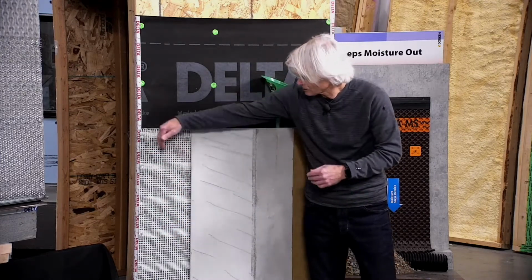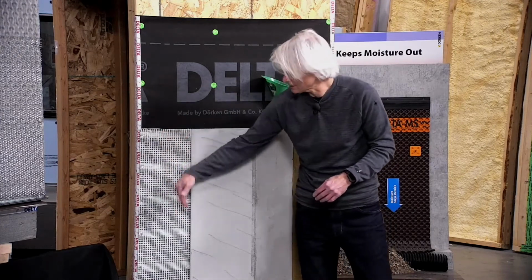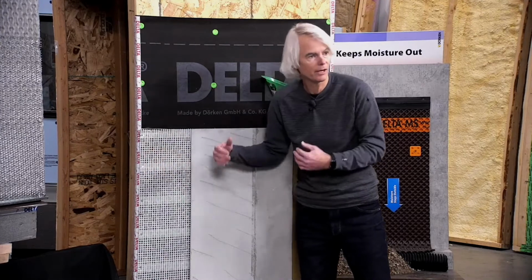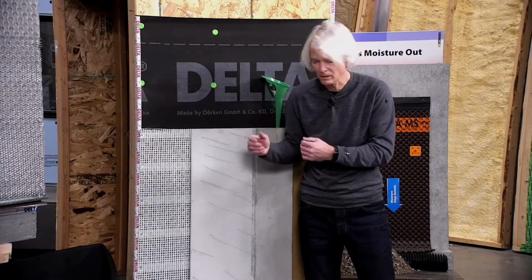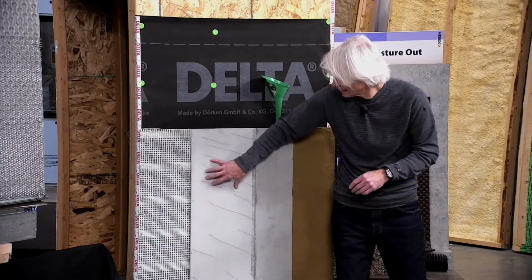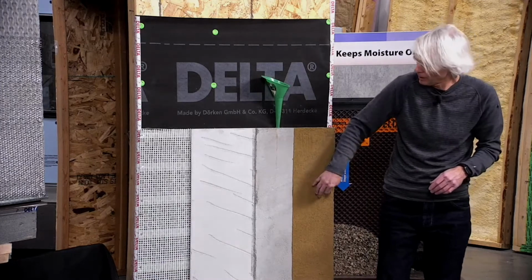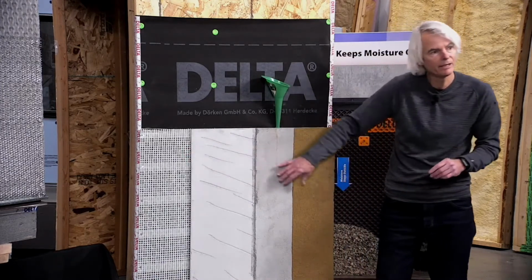So what we like about this product is you can see where you nail it, but you also see this grid pattern that you can easily sightline where there might be a stud or another accessory that's going on to kind of help level things out, should you level this product out right from the start. Now the next, we go from the scratch coat to the brown coat all the way over to the color coat, and we've got pretty much a completed assembly here.